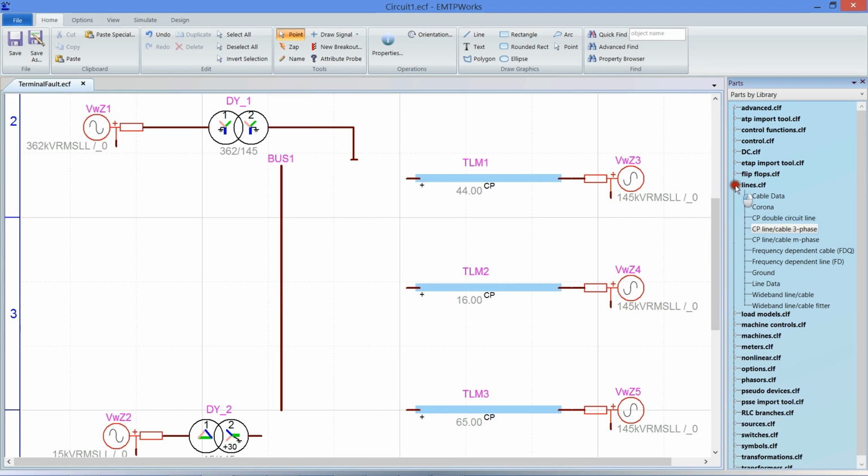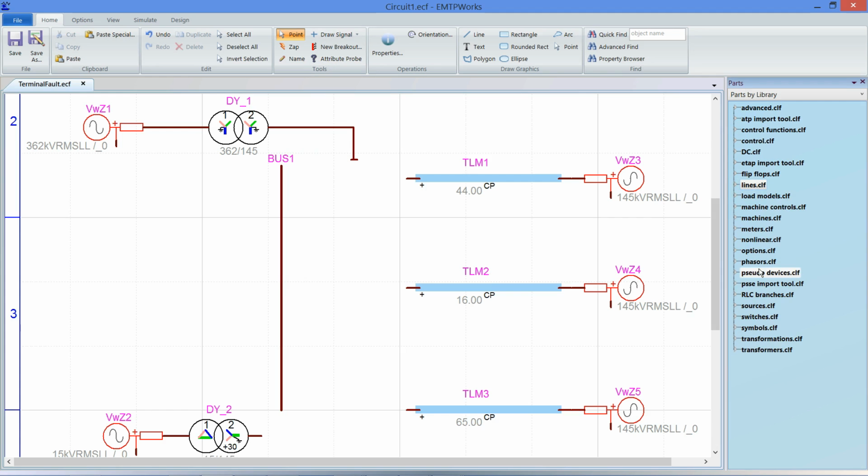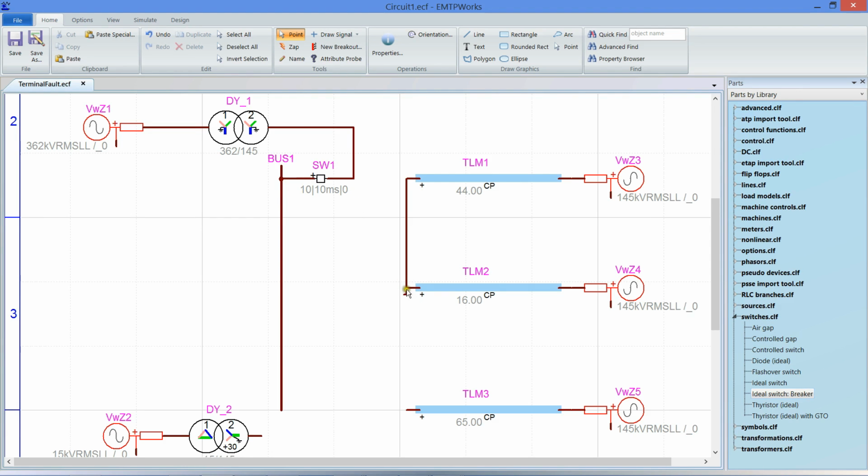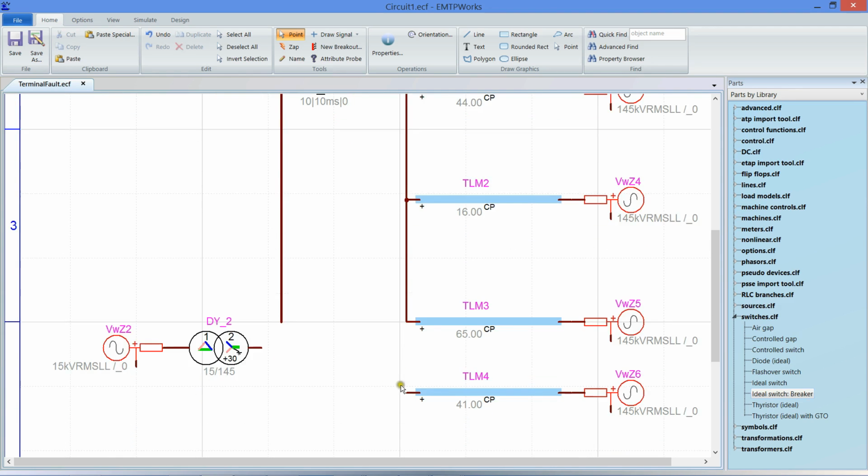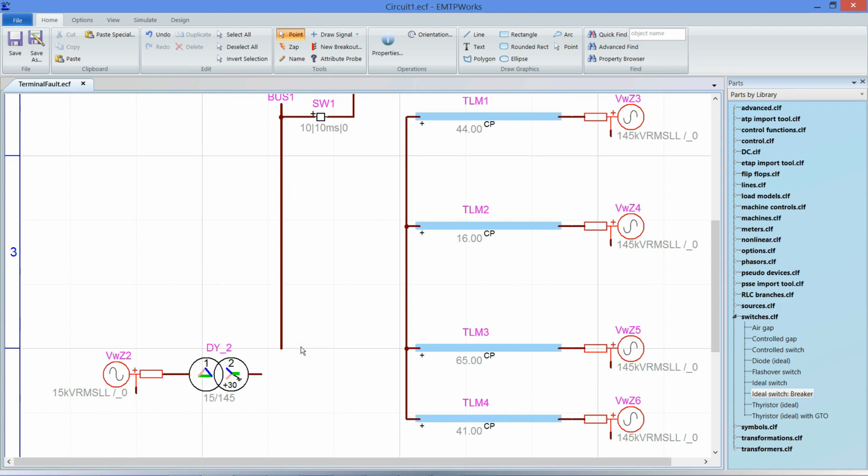Then, to reproduce the breaker during a TRV, the standard specifies to take an ideal switch. So an ideal breaker is the model to take to do TRV. In EMTP we have more advanced models. If you want to be even more precise, we have models that reproduce the pre-strike and the reignition, or even the arc model, so we can get very precise. Of course, after that you need more parameters to set those models. But again, if the goal is to respect the standard, it specifies to take an ideal switch.